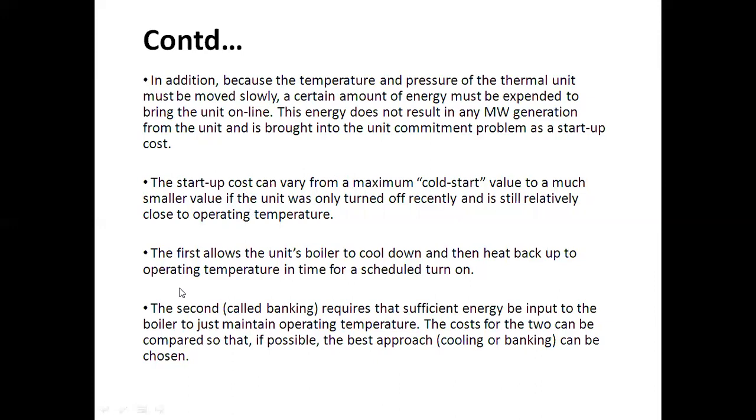The first, the starting case of the startup pause, allows the unit's boiler to first cool down and then heat back up to the operating temperature in time for a scheduled turn on. The second is called banking, which requires sufficient energy input to the boiler to just maintain operating temperature.